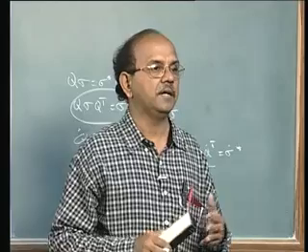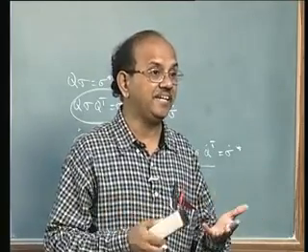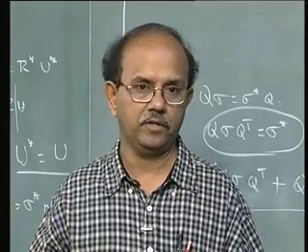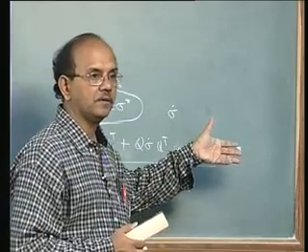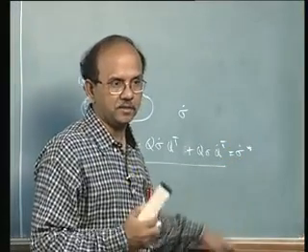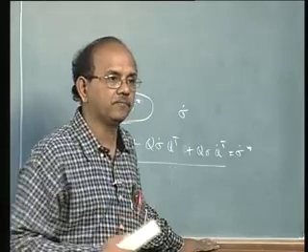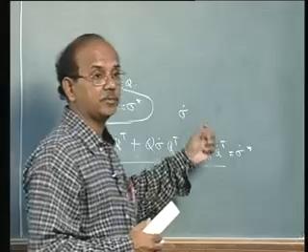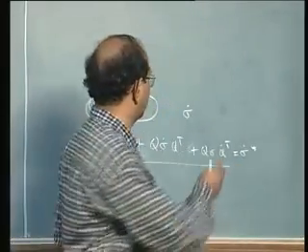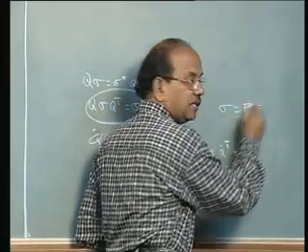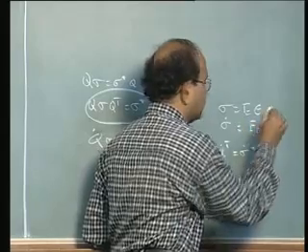Can I relate, say, epsilon dot and sigma dot, or D and sigma dot, in a constitutive equation when rate of loading becomes important, where many of the nonlinear equations are written in a rate form? Rate form means that the derivative with respect to time goes into the constitutive equation. It is not written as sigma is equal to E epsilon, but most of the time as sigma dot is equal to Et epsilon dot.